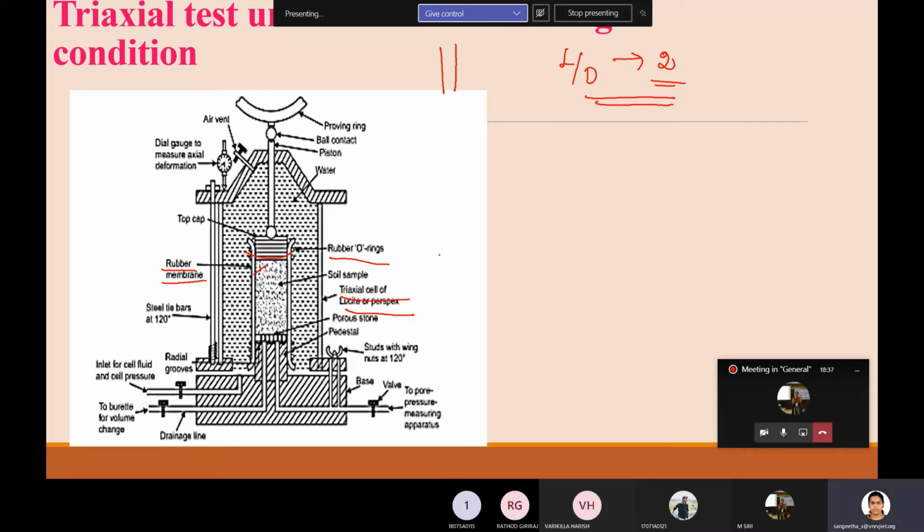your triaxial cell. So what is a triaxial cell? It is a cylindrical cell made of perspex glass. So you can actually see your sample through this glass. You can visually see what's happening, how your sample is bulging or how your sample is failing. That you can monitor. This sample setup is kept inside the perspex glass cell, and at the top a cap is provided,